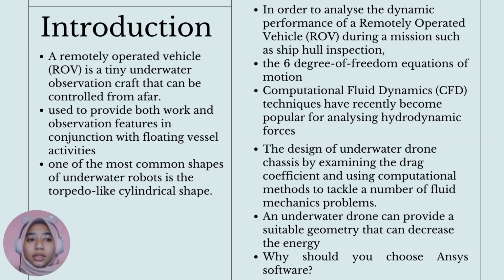In order to analyze the dynamic performance of a remotely operated vehicle during a mission such as ship hull inspection, the 6-degree-of-freedom equation of motion must be constructed while a well-modeled hydrodynamic force operating on the ROV is taken into consideration. CFD techniques have recently become popular for analyzing hydrodynamic force operating on a moving underwater vehicle.